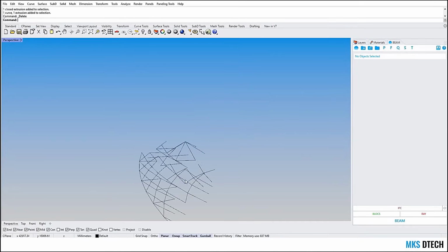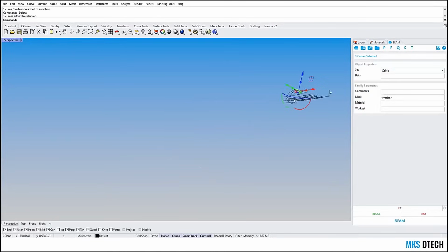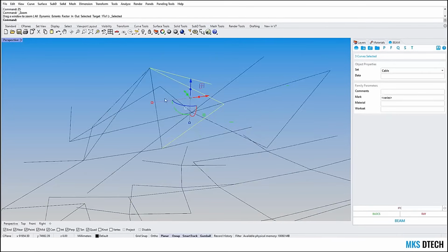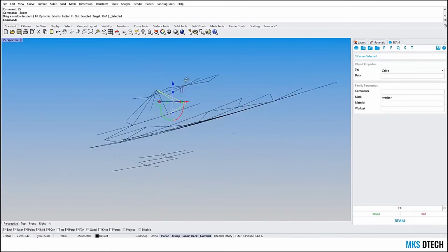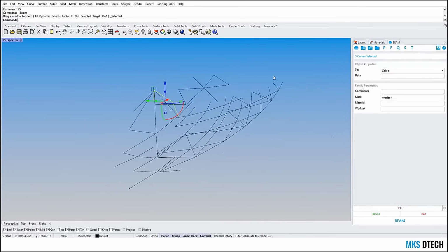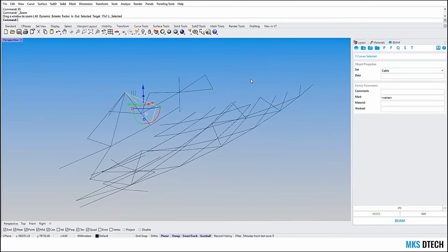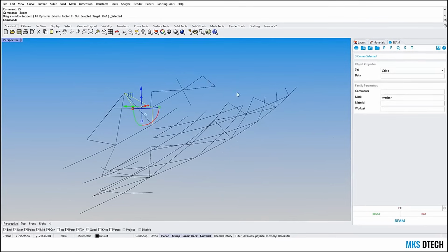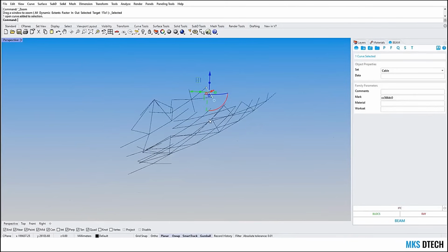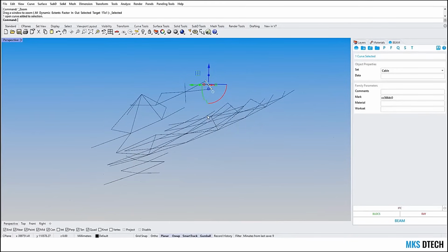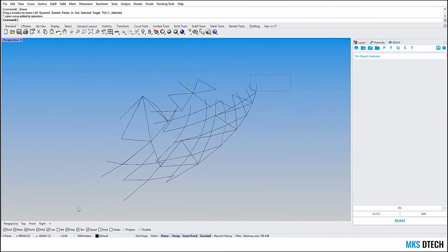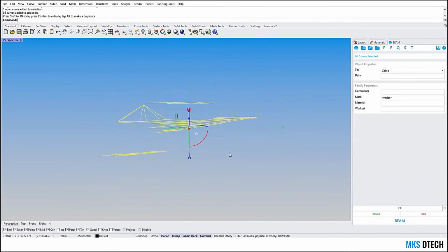And as I said at the beginning, the workflows that involve lines are super fast. So basically, in no time, you have all your lines in the Rhino file, and the name is the name of the family, and you have the mark assigned. So that basically can guarantee that we have a link between Rhino and Revit.